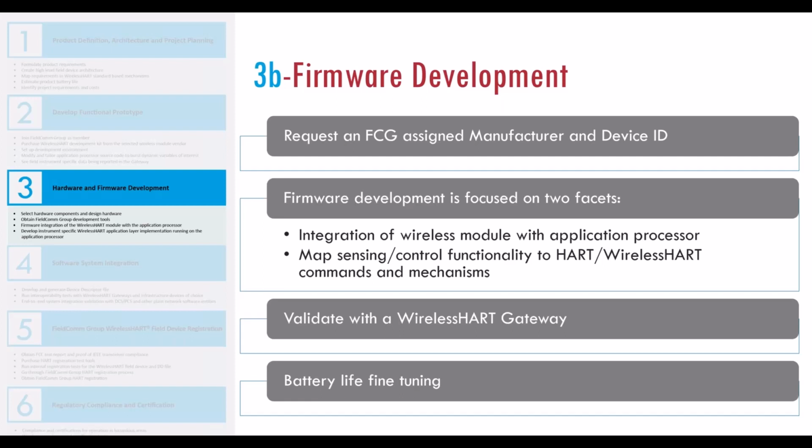But it is here that you would actually write some sort of a power scheduler to where you would fine tune when you would wake up the application processor, read your sensors, or control your actuators or your relay outputs or whatever you're doing, and also sync with the WirelessHART module in terms of publishing the data that you've collected or receiving data for your actuator.